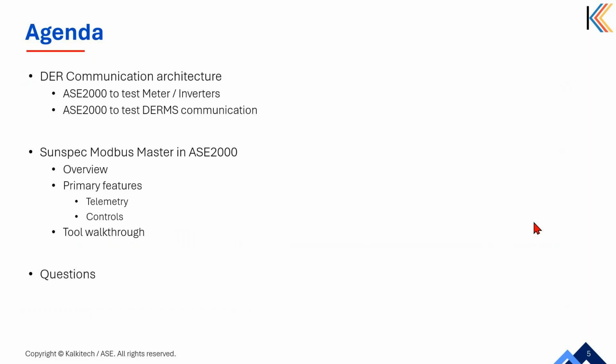So with SCADA and the substation, as you were alluding to, you have controls and you have masters and RTUs or outstations. What's the master in a DER application? In the case of DER systems, generally the DERMS will be like a control center monitoring the entire network. From each site, there will be gateways reporting the data to the DERMS, and DERMS will also send the schedules to these gateways. And gateways will finally pass the information to the end devices with protocols like SunSpec Modbus.